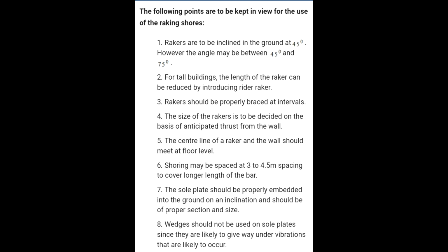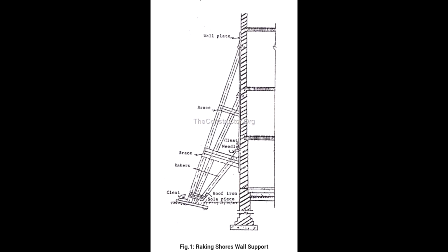The sole plate should be properly embedded into the ground on an inclination and should be of proper section and size. Wedges should not be used on sole plates since they are likely to give way under the vibrations that are likely to occur.